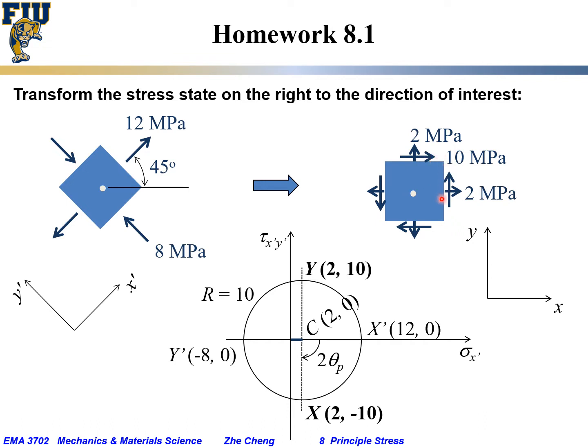So now you see tensile stress of 2 megapascal along the x-axis, tensile stress of 2 megapascal along the y-axis, and shearing stress 10 coming together here. So this would be the transformed or rotated stress that is equivalent to the original stress state that we drew here.